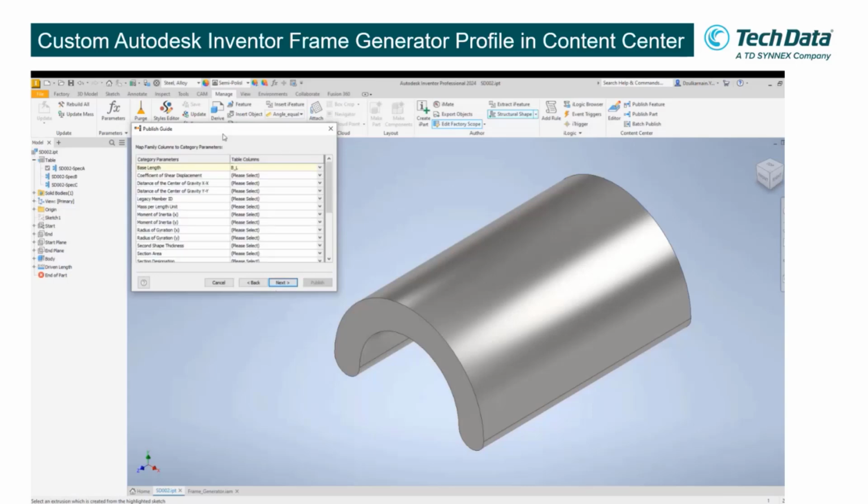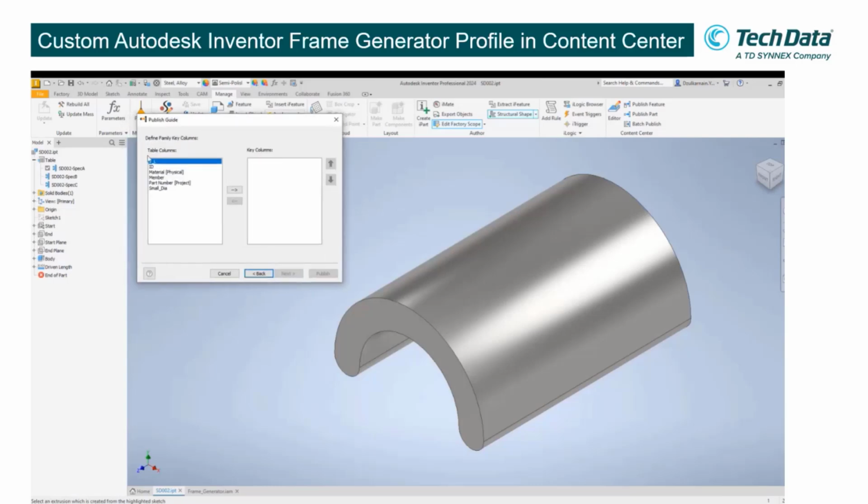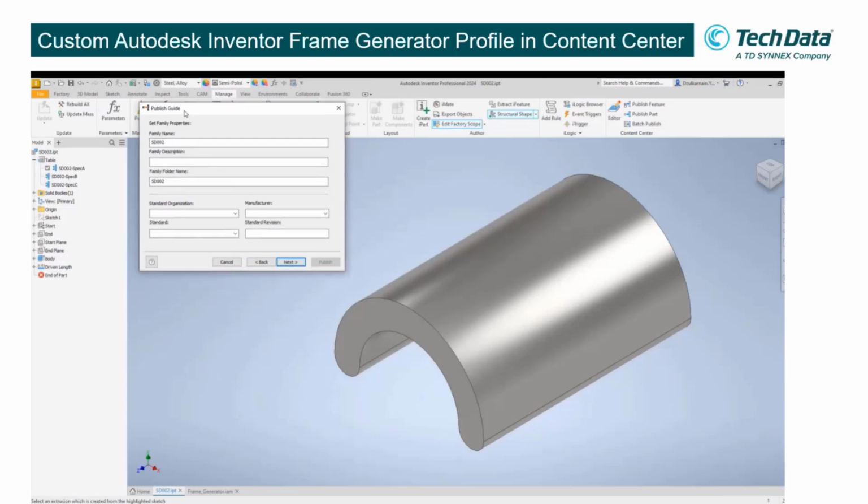Next, just double check. The rest is more like double checking. So base length, correct. Next. Under table column, we define the family key column. This is the information that we want to see whenever we want to change to a new size or new specs. In this case, let me just add all the BL, ID, member, part number, and small diameter parameter as key columns. We can add more after. Then specify the family name: what is the name of this new steel structure? Descriptions: custom frame generator.